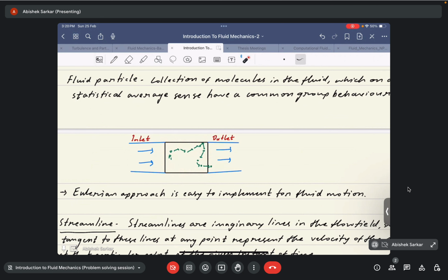But in this case, obviously you can see it's just the trajectory of one particle. Even if we are going to model numerically a single particle, it would require proper modeling of the trajectory of these particles throughout the flow. And if the flow is turbulent, that itself causes a more highly expensive computational setup, right?